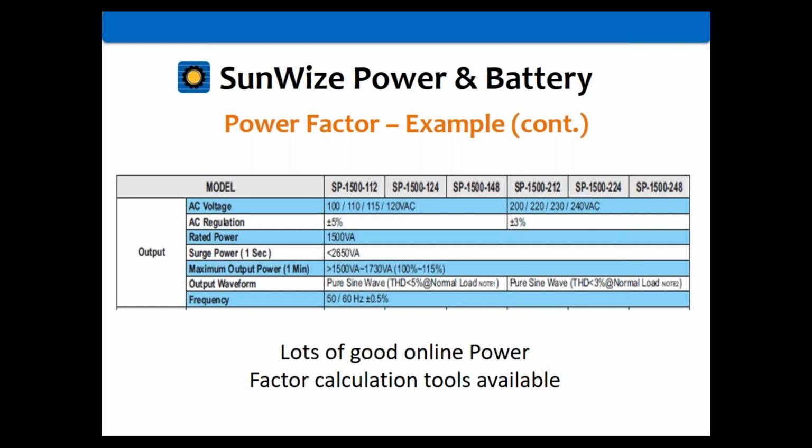So also keep that in mind when you're looking at an inverter spec sheet. Look at these numbers. Is it a 2-wire or a 3-wire inverter? If you've got a 120, 240 load, does my load have a power factor that's going to be an issue? Do I need to worry about those volt amps?